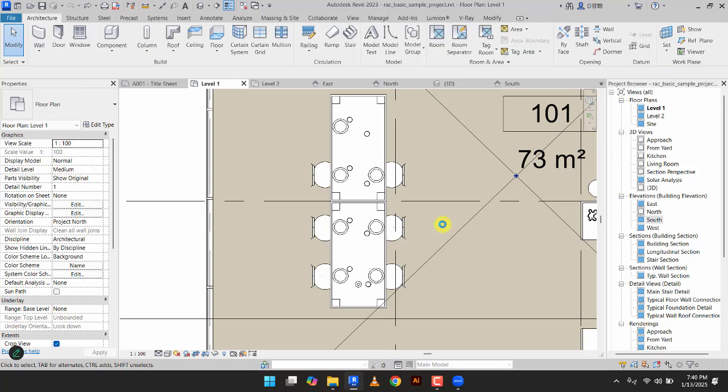So you can delete anything you want except a pinned object. If an object is pinned, you can't delete it. Just like putting something on the notice board, putting a pin in it to not fall unless the pin comes off. So if something is pinned, you can't delete. If you start your own project, nothing is pinned unless you pin something. There are times you download something online you want to use in a project. You select it, you realize you cannot make some changes to it. It means that object is pinned. Just unpin it. I just click, then it's done.